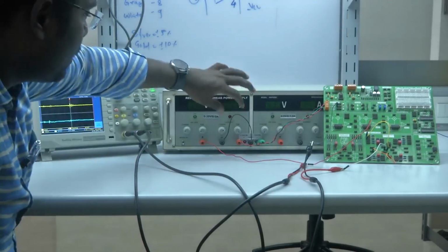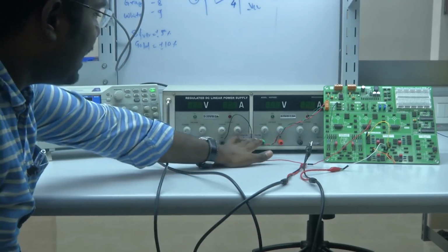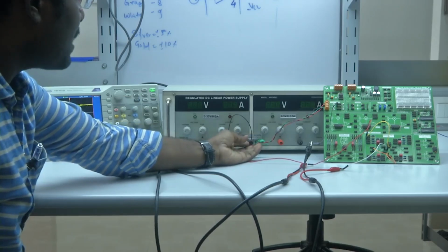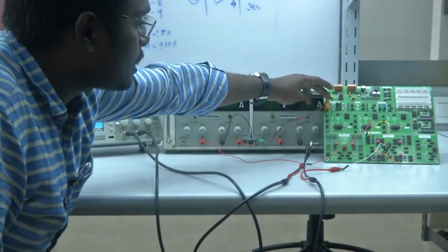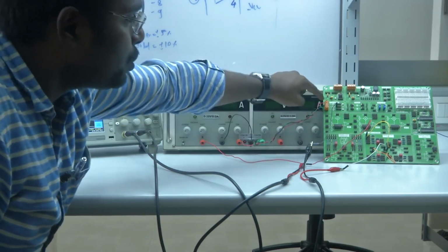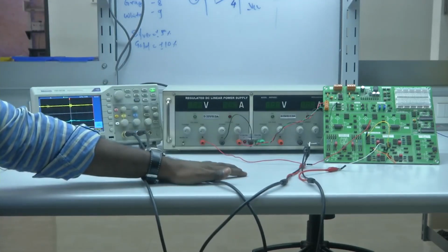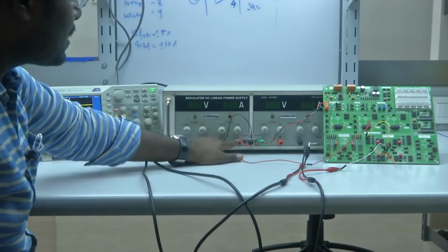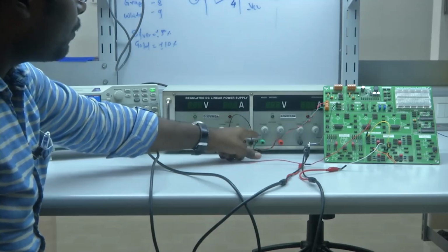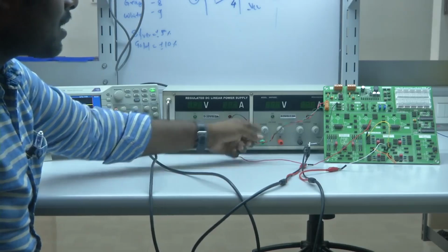So, what we have made: the DC linear power supply that we have has dedicated power sources for plus 15, minus 15 and ground. We have connected the plus 15 to the main power, one side, which is the positive terminal. Even though the board shows plus 10, minus 10, we have connected 15 because the operational amplifiers can withstand up to plus or minus 18 volts. Since we have a dedicated power supply, we have directly connected it, and for the negative, the green wire has been connected to the other side, and the ground, which is the common terminal in this case, is connected.